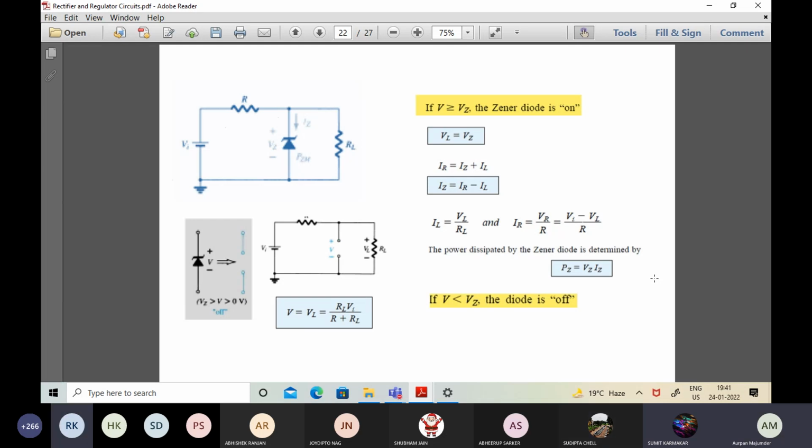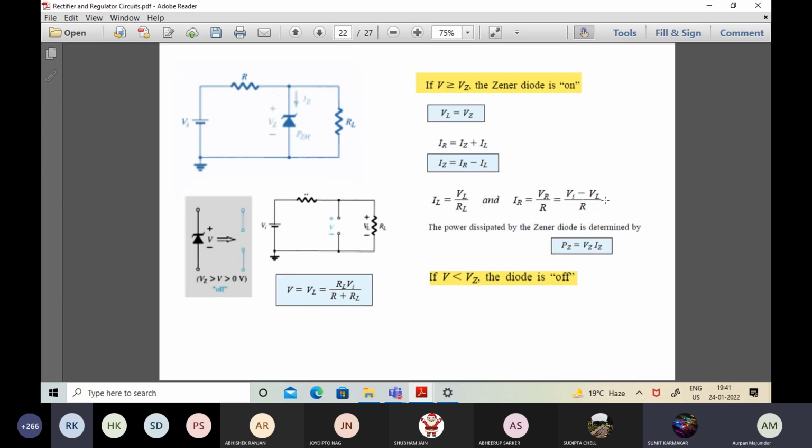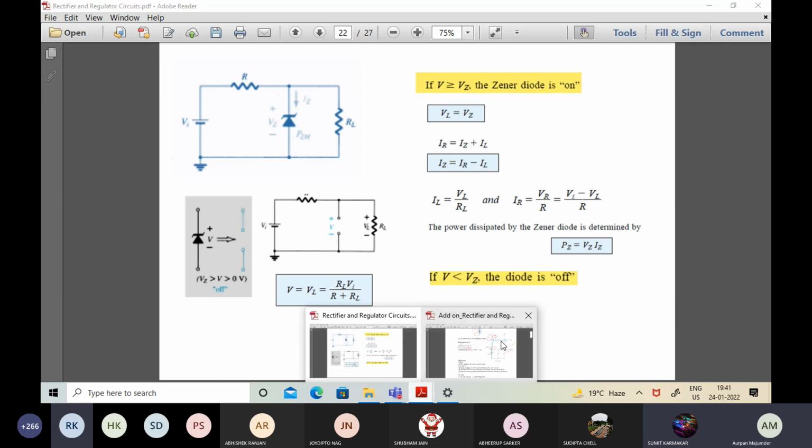Actually, to be more frank with you, the value of RZ is even lower compared to the forward bias context. If I talk about RZ, keep in mind that RZ is applicable as the incremental resistance under reverse bias. So just follow the ones which have been shown in this particular slide. It has been clearly mentioned what the paths of the flow of current and the various equations are. Let's take up, for the class discussion, the one from the analog electronics domain.